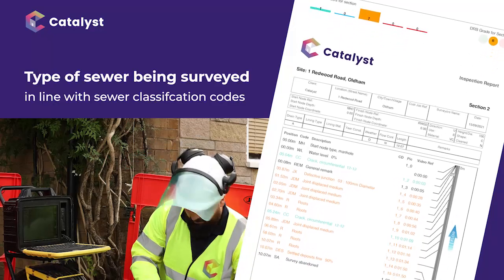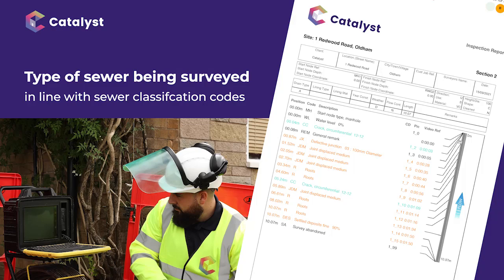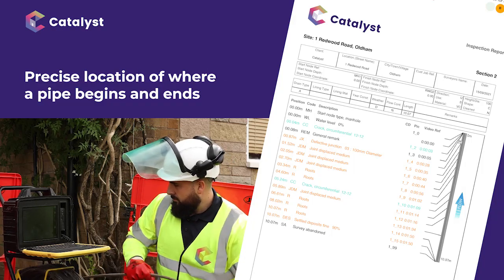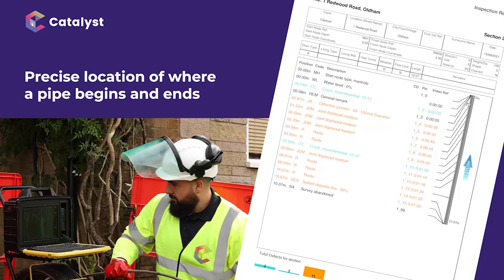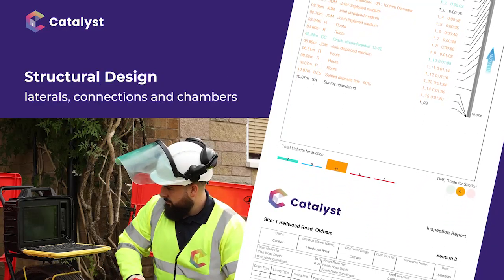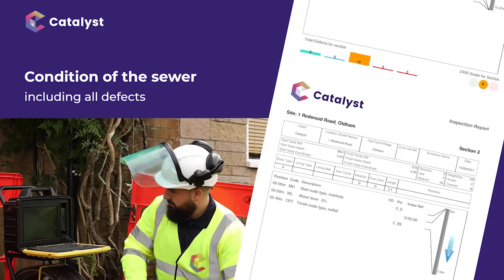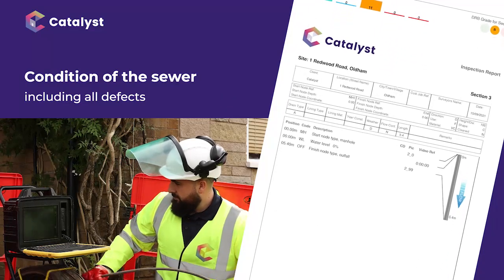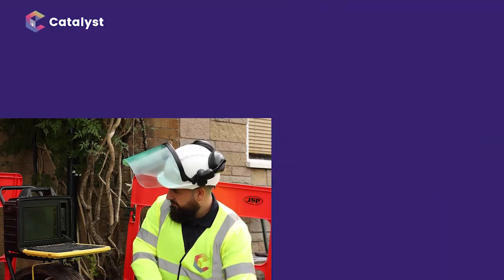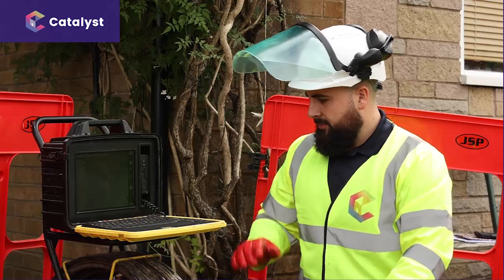They record the type of sewer being surveyed in line with the sewer classification codes, the precise location of where a pipe begins and ends, the lengths of pipes in meters, structural design such as laterals, connections and chambers, and crucially, the condition of the sewer, including all defects. The drainage engineer records all this data by inputting specific codes.